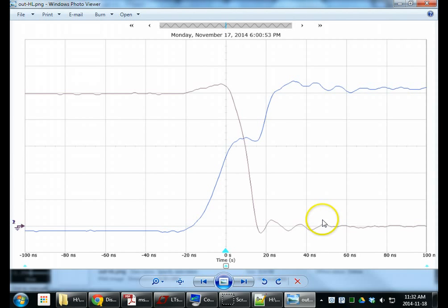When we construct this, there's an extra capacitor, as you see, that is strapped across the power supply. From a schematic point of view, it makes no sense. But what happens is these charges are trying to flow really fast. The currents are changing really fast. Our wires from the power supply are really long, as in they're kind of big inductors. Well, if we put a capacitor right across where we need the charge to come from, right at the power supply nodes on the breadboard, then it makes this look a little better.